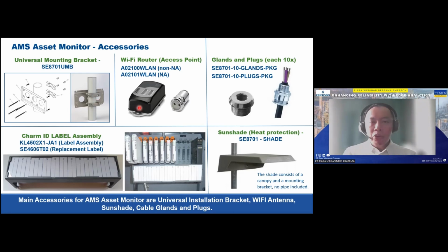In terms of the connectivity, this is optional. You can either use a LAN cable, but LAN cables have a limitation of 100 meters. If the distance is more than 100 meters, you might want to consider using wireless. So it's also available using a wireless router. And other than that, all these are inclusive in the package: cable glands, labels, and so on. This is optional, a sunshade. If it's exposed to the sun, maybe you might want a sunshade.